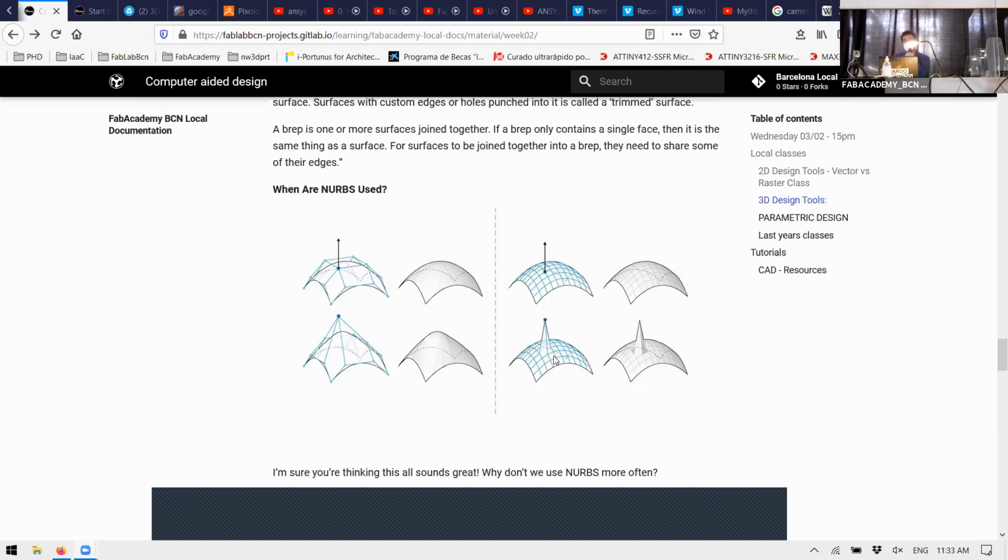Meanwhile, if I select a dot on this surface, it is clearly defined. That surface is defined by four, and minimum three, points. With these three points, I can calculate the location. It's like GPS triangulation. So you can know exactly what is the spatial location of that one. So for example, mesh formats have higher three-dimensional accuracy than NURBS. So if you want to make something that is accurate, or have a physical representation of it in an accurate way, you want to do it with a mesh. You don't want to do it with a NURBS, because in a mesh, it's way easier to measure than in a NURBS.